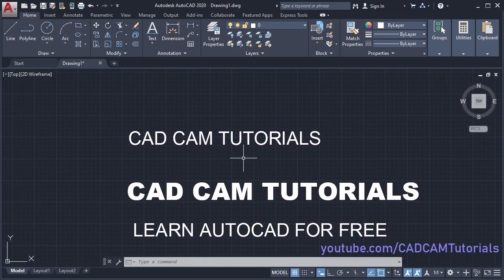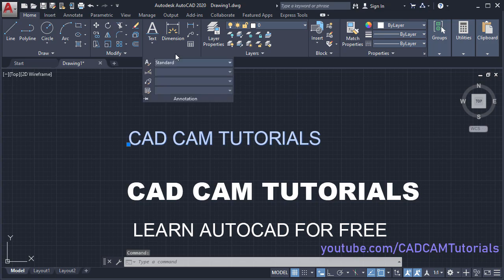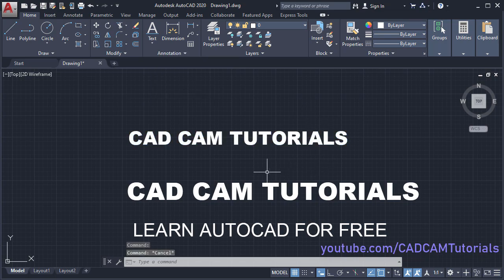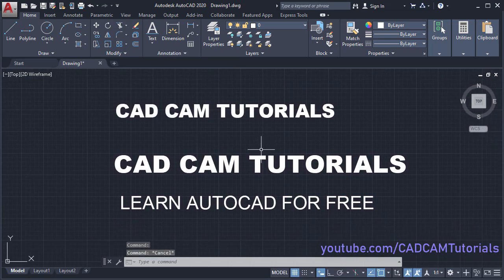And suppose you just want to change font, then you can also change font by selecting the text. Then click here on annotation and click here on standard, and from here you can choose your desired style. Suppose again I will click here on style 1, press escape. In this way also you can change font.